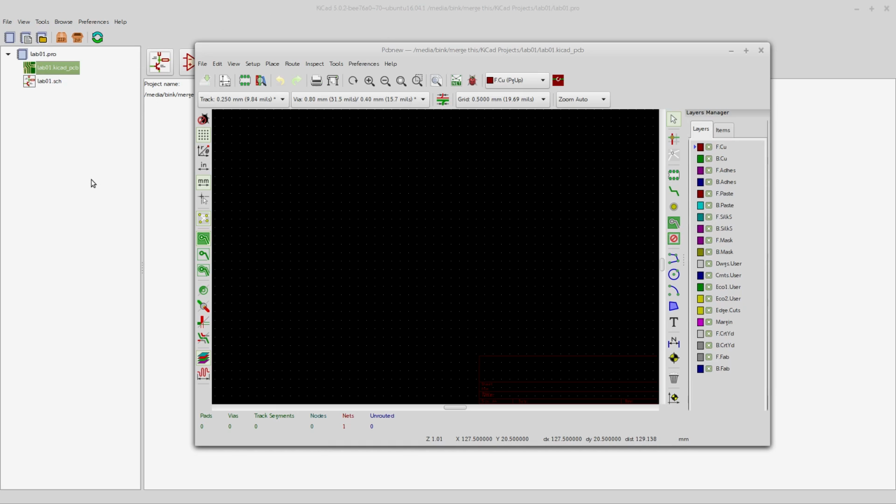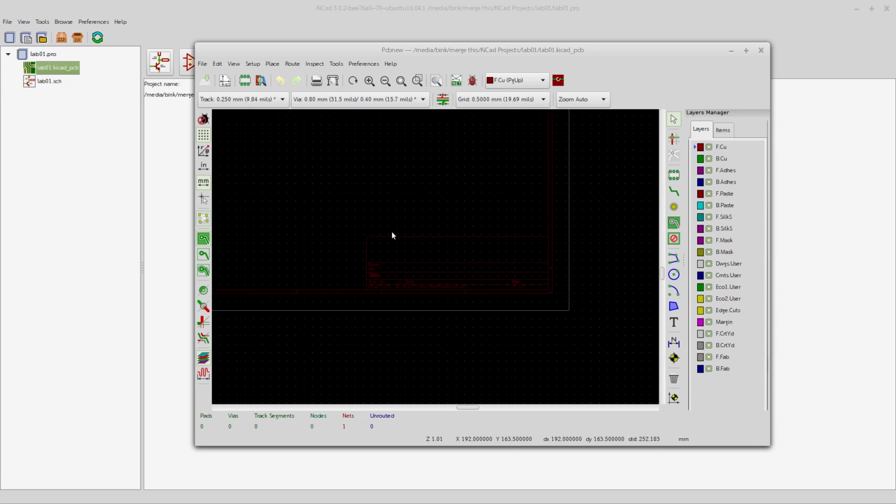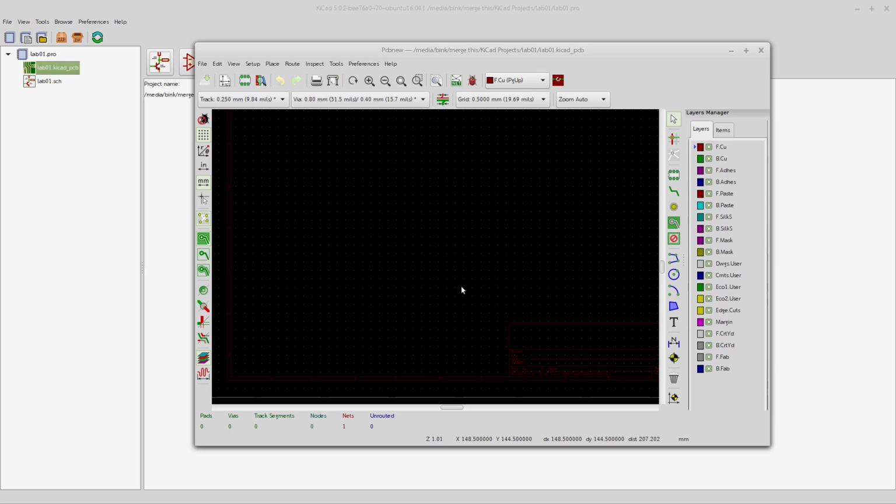So typically you end up opening all three of these. You always have the main project window open in the background, and then you'll have the PCB and the schematic open at the same time, and you bounce back and forth between the two. In a perfect world, you'd make the schematic, everything would be beautiful, and then you would save everything as a netlist, open it up in your PCB editor, route your traces and you'd be done. Reality is you usually forget something, you want to change something, there's a little mistake, or maybe the rules checker says that, oops, you forgot an open trace or something, and you have to go back and fix it. So you end up with both windows open and you bounce back and forth.